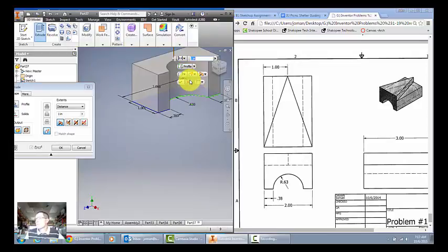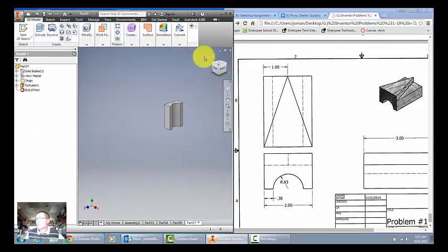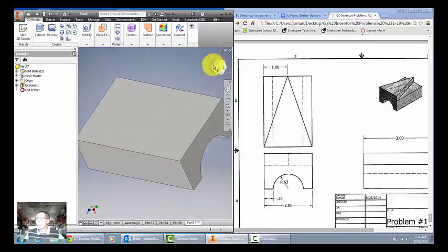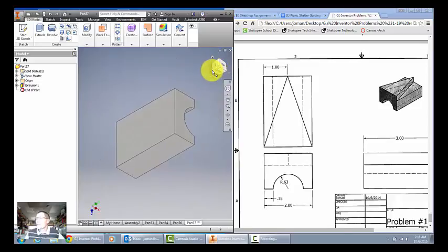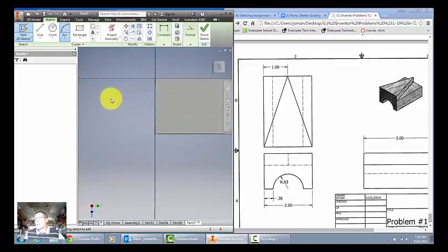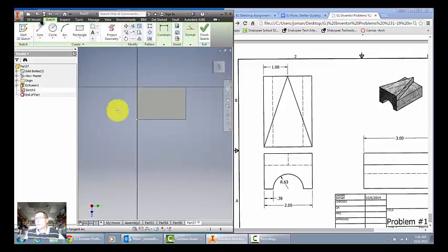We'll extrude it. And we're going to extrude that 3 inches. Looks like I picked the wrong plane to draw it on, but that's alright. Okay, and the final sketch is a triangle on top. Okay, we don't have to measure much here, we just start in the corners.